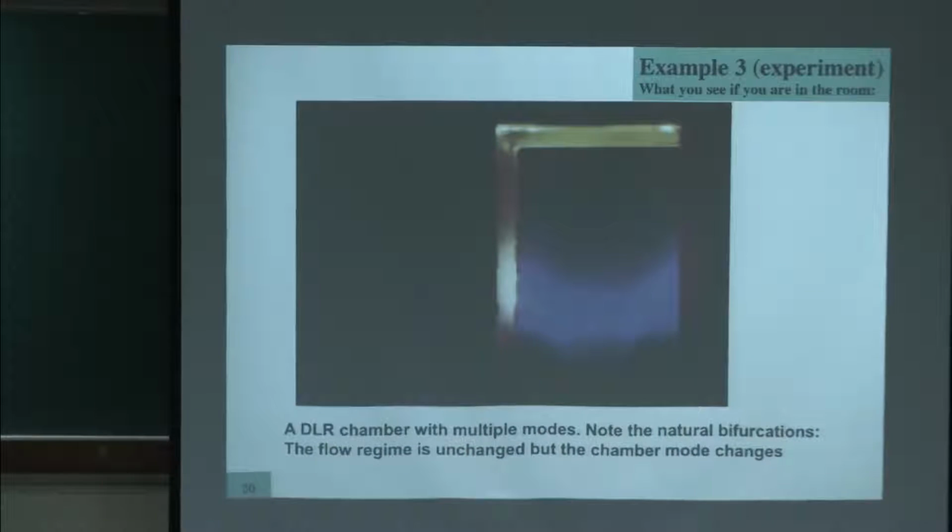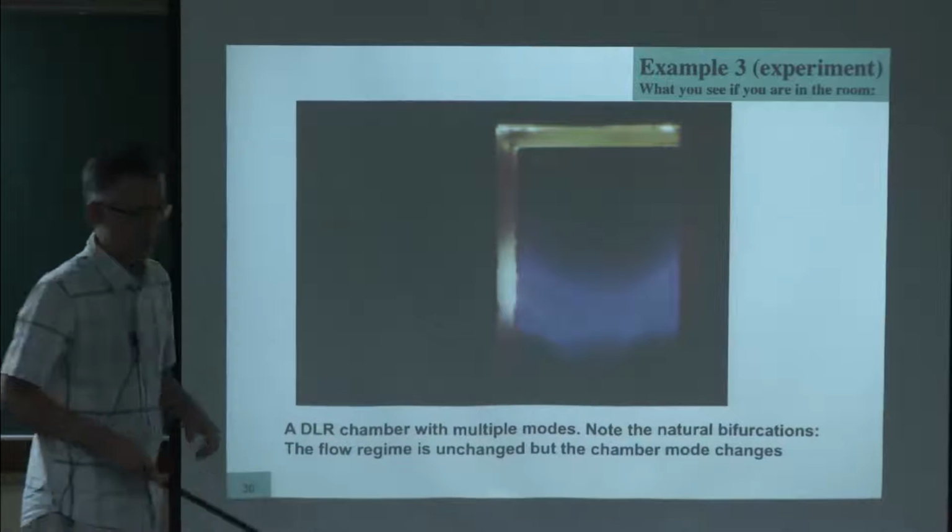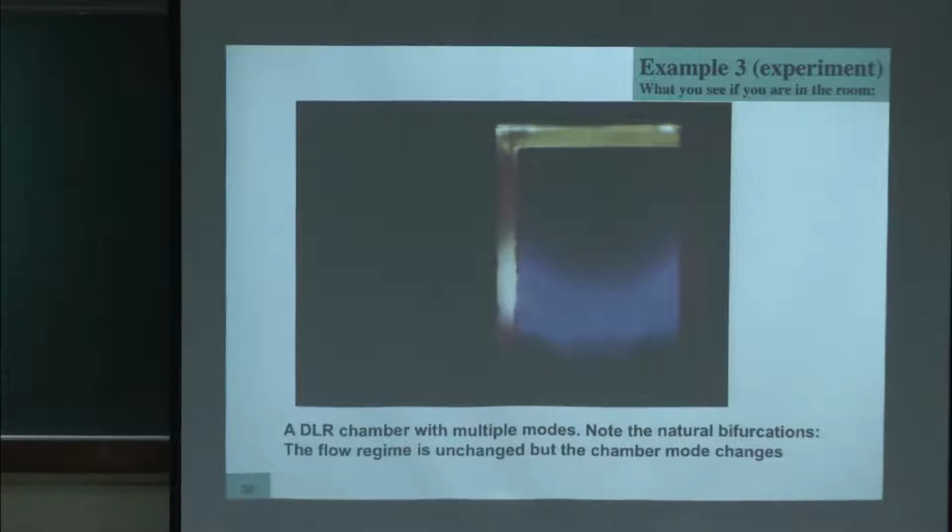Now, another thing which is interesting with instabilities is that even instabilities are unstable. You will hear for this burner, where the flow is injected here, it's a swirl burner, you will hear multiple noises. Don't change anything, it's the same regime. And so then you can talk to people, Sujit here is a big specialist of that. You can have bifurcations during instability. So if you listen to it carefully, you will recognize different modes now.